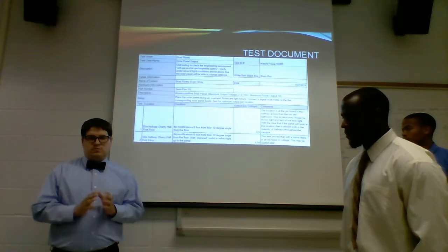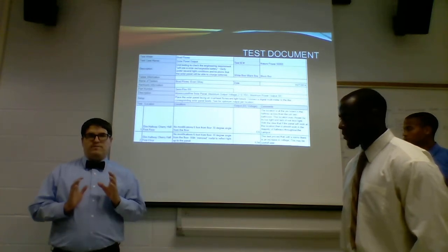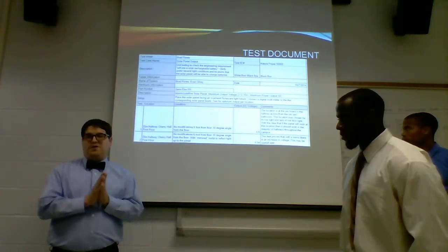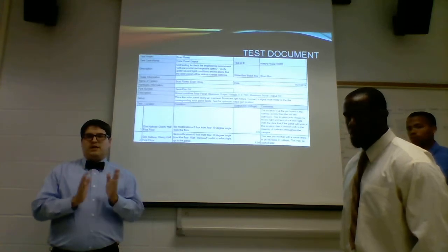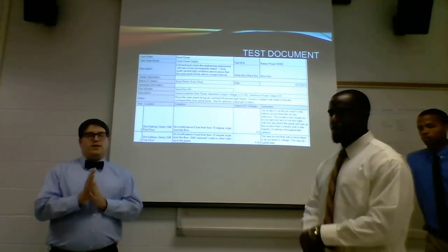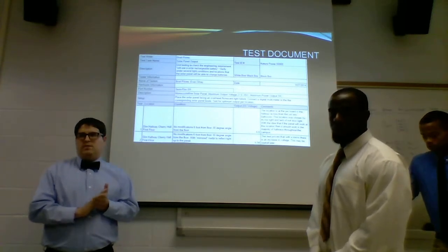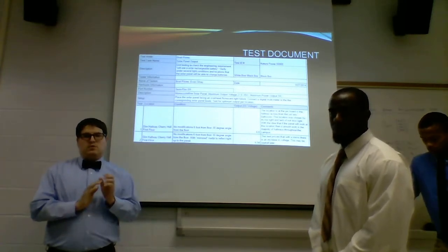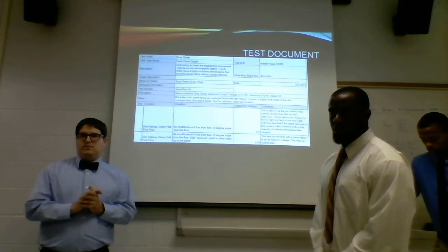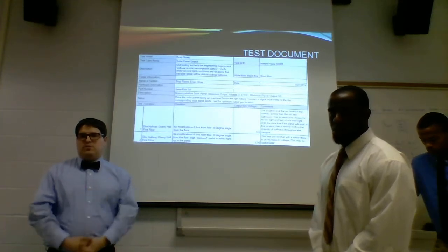So we took the solar panel, found a dim spot here in Cherry Hall, and tested the voltage. We got approximately 6.6 volts DC, and we noticed that there was an LED circuit attached to the solar panel.